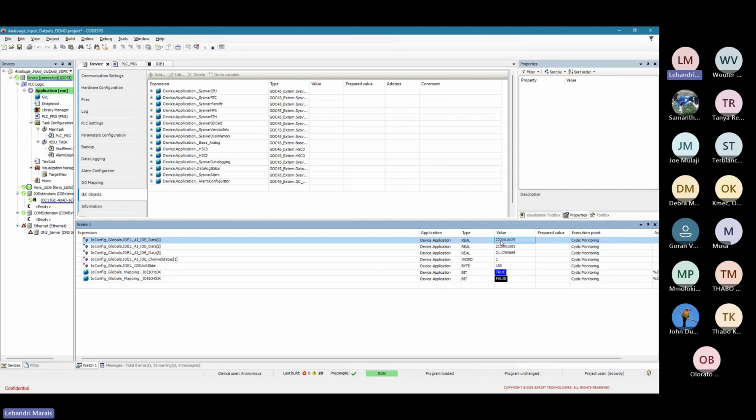So the analog value that comes in is converted to a value from 0 to 64,000. Whenever you add scaling, it takes the value out of 64,000 and scales it to the range you want it to be scaled to. I hope that makes sense.